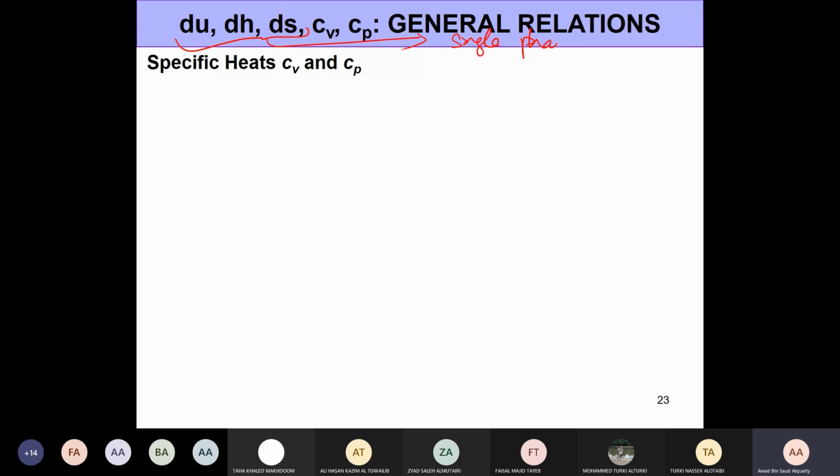When we are dealing with a phase change, the specific heats are not even defined, and we need to rely on the Clapeyron equation to obtain the change in enthalpy hfg, or the change in entropy sfg. Then we can use hfg to determine ufg as well, simply from the relation between hfg and ufg.